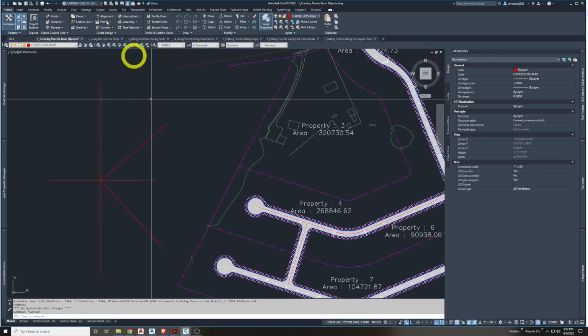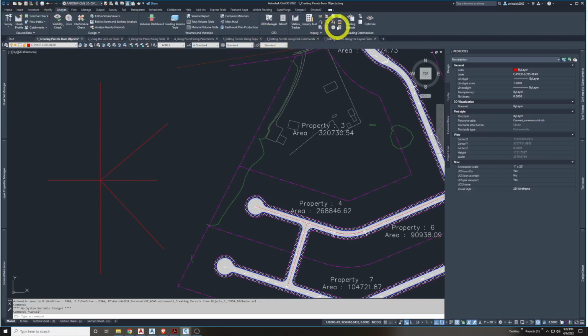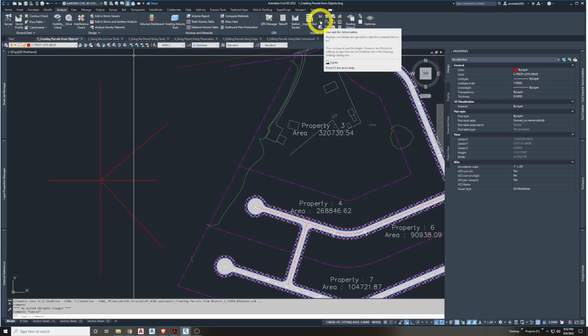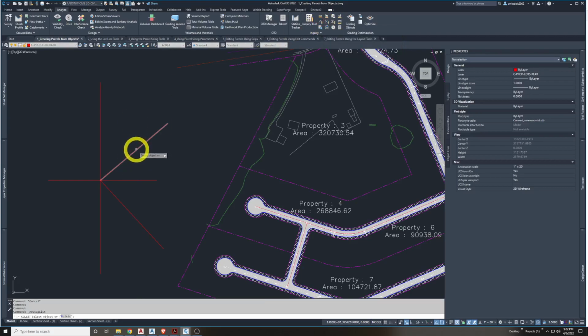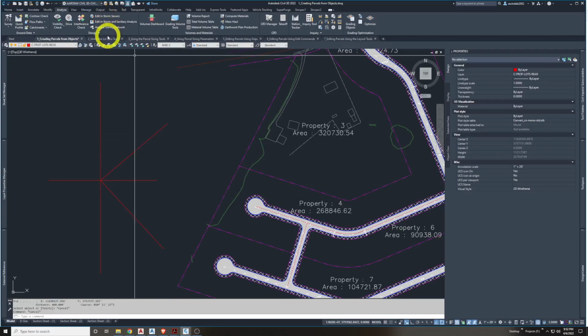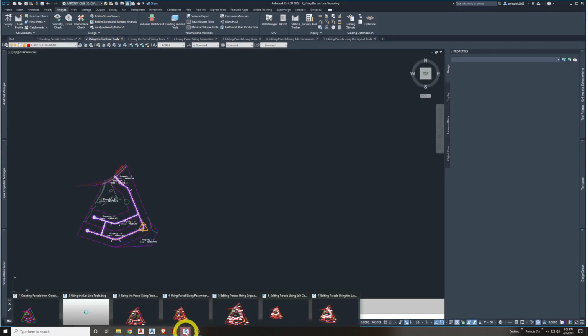So if I do a CG list, or if I go to Analyze, and I use some of my Analyze inquiry methods here, let's hover on a few. We got distance and area, angle, we got slope. Really, the one I want is this one that gives CG list, a little more land surveying friendly. And I pick it, and here I have my distance and my course, or my bearing, 50 degrees, 11 minutes, 27 seconds east. So I can verify I drew it exactly. So that's a little bit of 101 on that. That's a little extra that helps you draw like a surveyor.